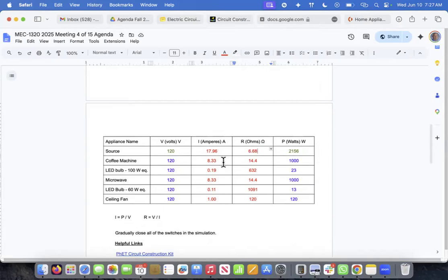Usually when a circuit breaker pops or disconnects or deactivates a circuit, it's one of two reasons. There's either a short, which is bad because that means the current's going in some direction that you don't know and it's quite high. Or it means that there's too much power being provided by that panel. There's too much current being drawn and it switches off because of that.